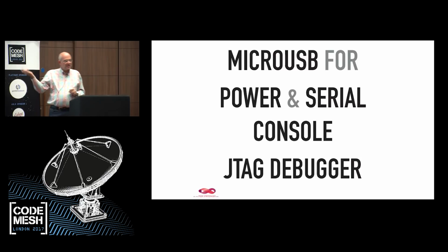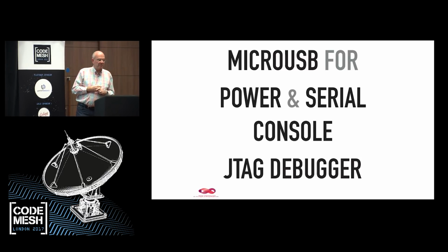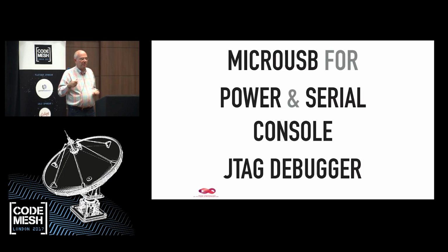And there's also a JTAG debugger on the device. JTAG is a kind of standard to actually test chips. But you can run a debugger with it. So you can single step and breakpoint the actual CPU. So you can, from reset, debug the first steps of the CPU with JTAG. And we built a JTAG debugger interface on the board. So all you need is a USB cable and a piece of open source software, which is called OpenOCD. And then you can flash the bootloader also and do all kinds of things.